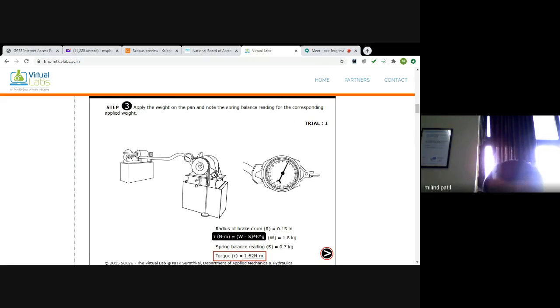Here, this is a drum which is attached to the turbine shaft. You learn in your theory of machines how to measure the brake power or shaft power. This we generally do by using a dynamometer. A rope brake dynamometer is generally used. Here is a dynamometer provided with this rope.